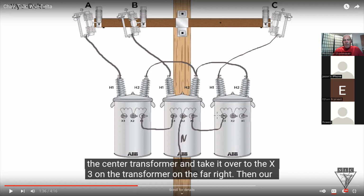Tie-in bus. Yeah, tie-in bus, right. Same thing now, except we're just using two. And he also explained here, this makes up my system neutral for secondary. I only need to do it one time. I don't need to do it to all three transformers. One is sufficient.